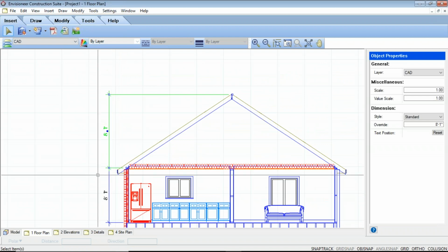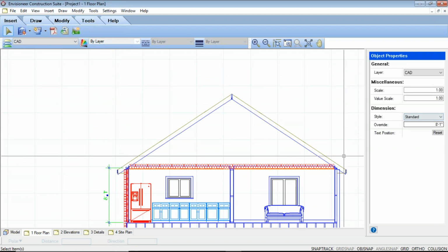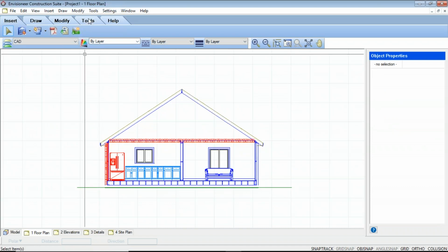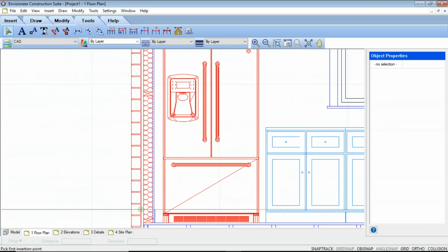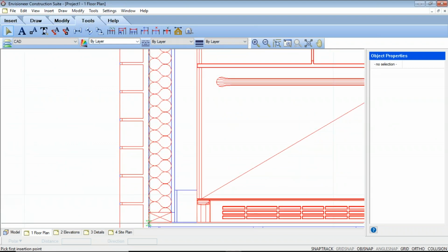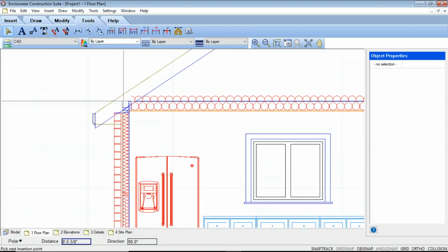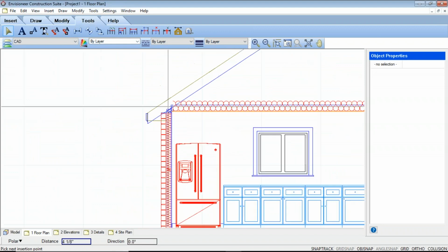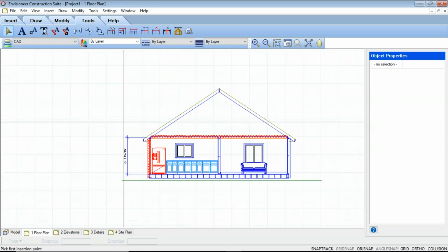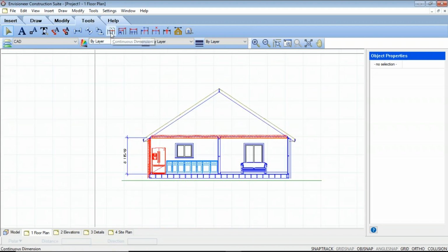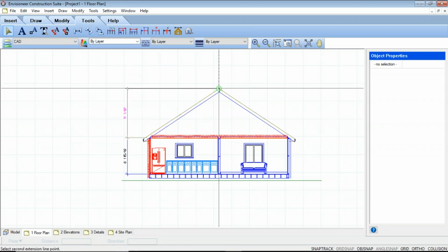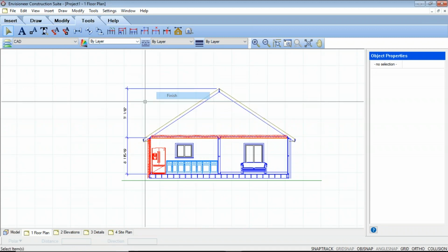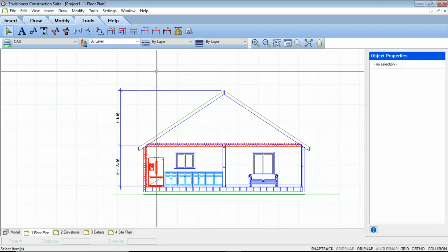And if I delete out this, and let's just reset. Actually, let's just delete this out. And we'll use the original dimension so that it's actually specifying the correct height. And we're going to go into here, and then up to here. We'll go there. And then let's say we want to do continuous. I select that dimension, and now it's going to find that new dimension for me and add that in.